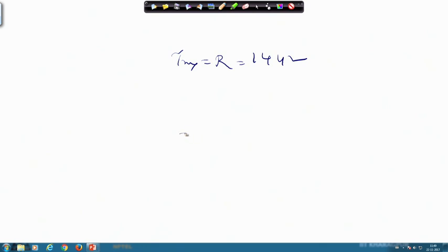If I draw the horizontal, the normal was at 16.85 degrees, that means the plane of maximum shear stress is at 45 degrees with this. So, I can go further to make 45, that is 28.15, from here to here I can go 28.15 and draw a line. So, this is the direction. On that direction I can complete the element, suppose this, and then on that element I can show the stresses.